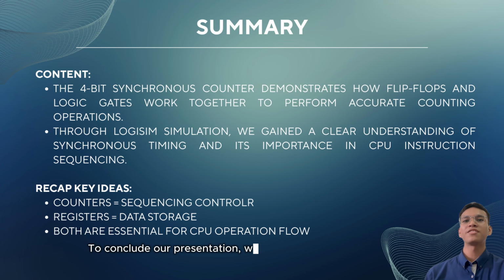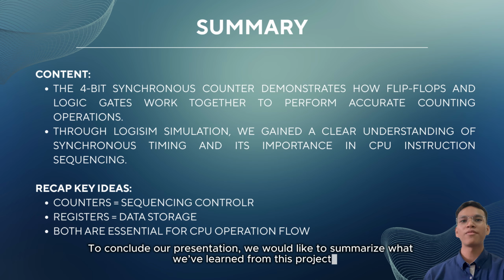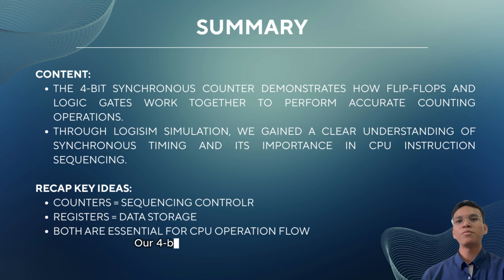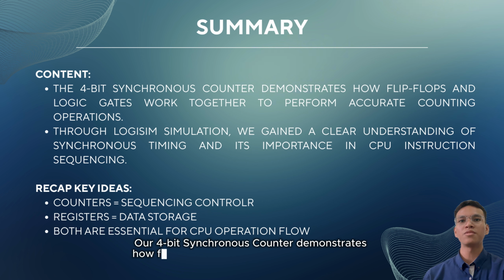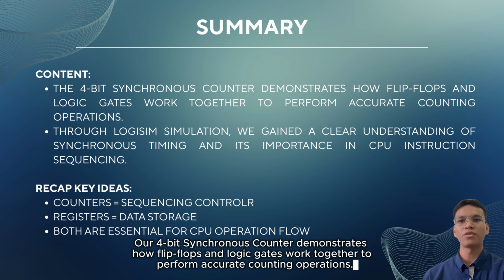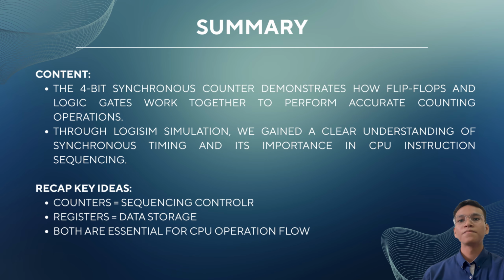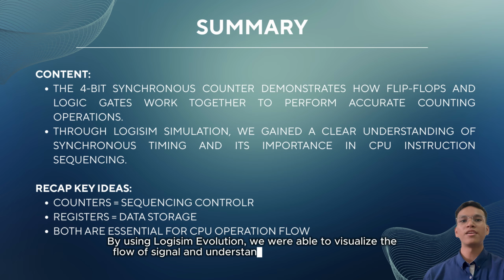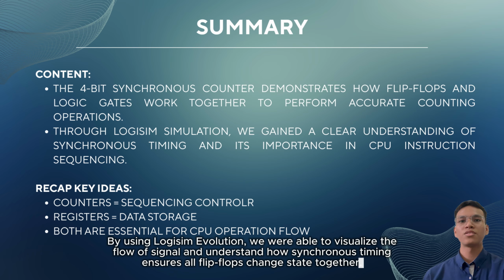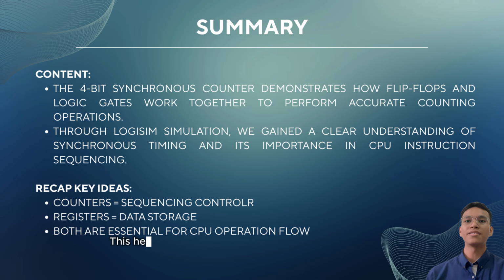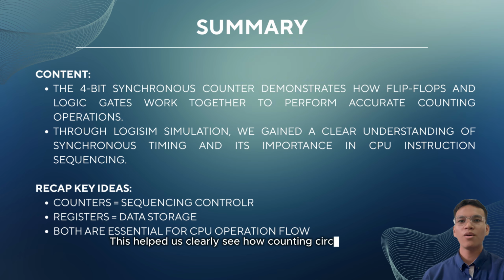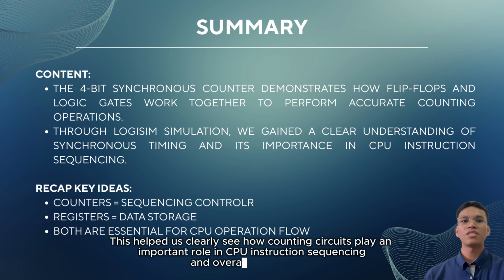To conclude our presentation, we would like to summarize what we have learned from this project. Our 4-bit synchronous counter demonstrated how flip-flops and logic gates work together to perform accurate counting operations. By using Logisim Evolution, we were able to visualize the flow of signals and understand how synchronous timing ensures all flip-flops change state together. This helped us clearly see how counting circuits play an important role in CPU instruction sequencing and overall control flow.